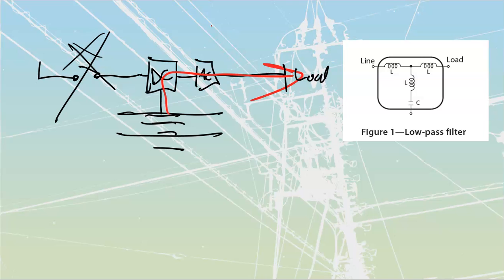We'll oftentimes use these UPSs when we are dealing with emergency systems, particularly if you've got critical data or hospitals or prisons or things like that, where you're going to have a UPS that's going to be coupled with your generator. So when we have a fault, then hydro gets lost, the UPS provides the ride through just for a couple of minutes, at the tops. Usually it's just going to be a couple of seconds, while the generator comes up to speed, stabilizes, and we switch over to that generator. It's just designed to have an operation that would be upstream.